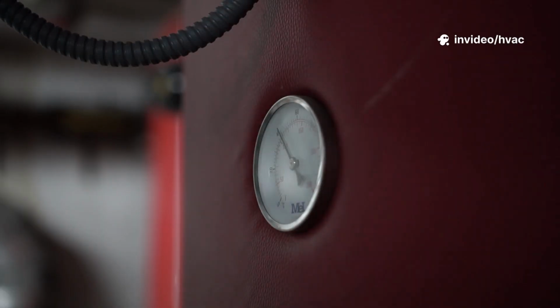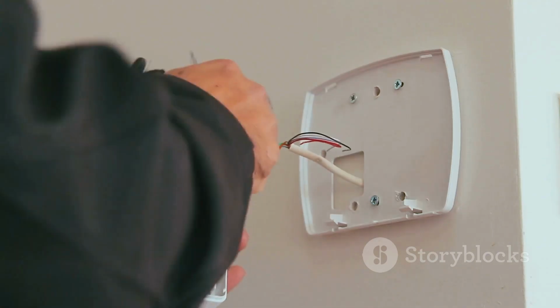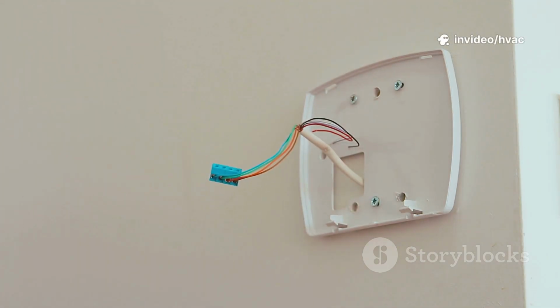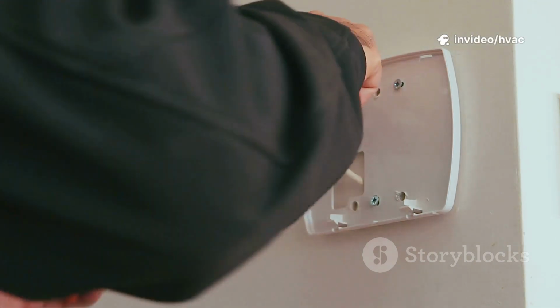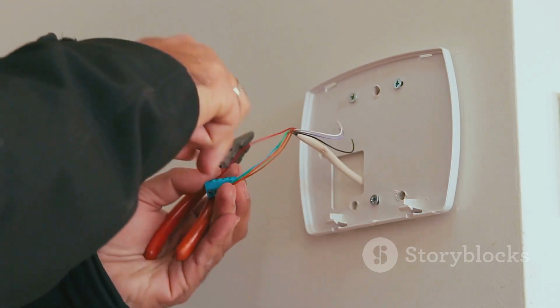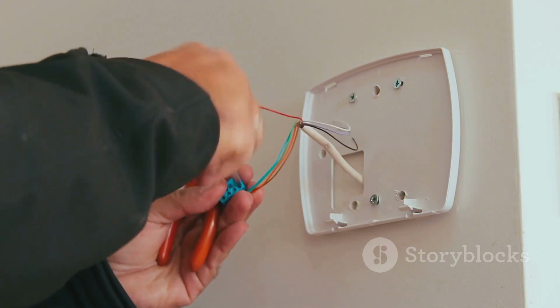Common mistake: don't leave the sensor coiled up in a corner. A coiled sensor only measures a small pocket of air, making your data unreliable. Always spread the sensor out for full coverage. For installation, use mounting clips or brackets provided by the manufacturer. Secure the sensor at regular intervals, typically every 2 to 3 feet, so it stays in place and doesn't sag. Make sure the sensor is not touching the duct walls directly, as this can affect readings.